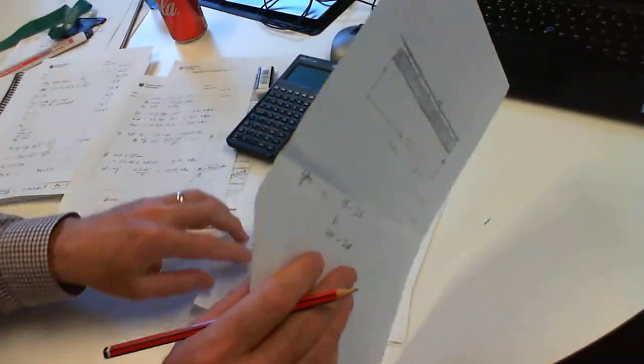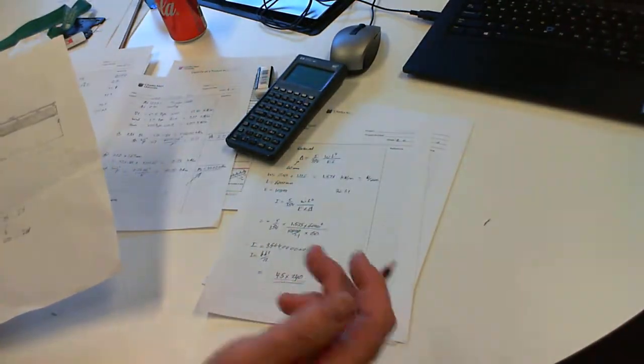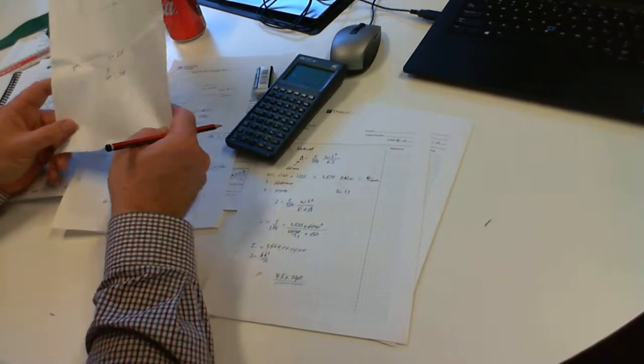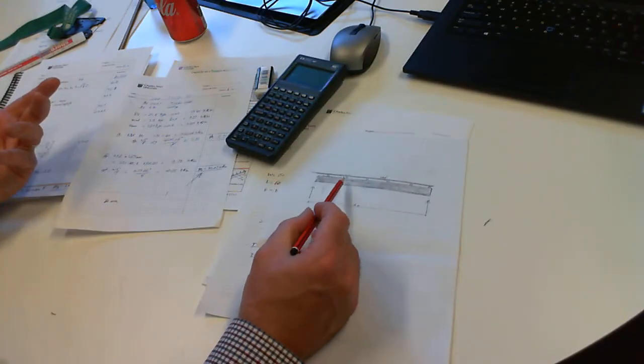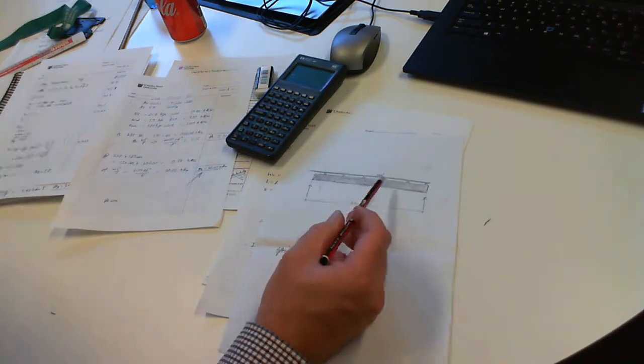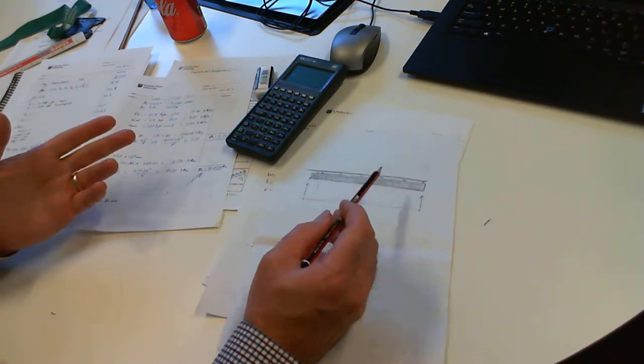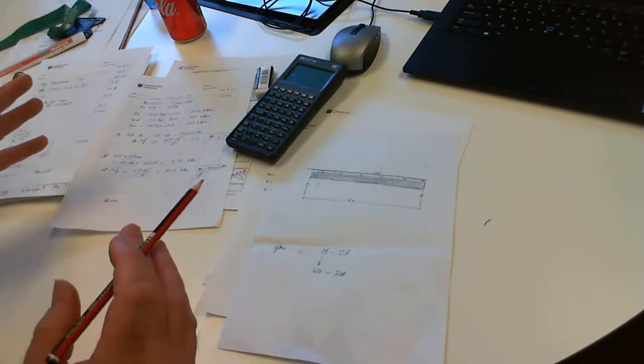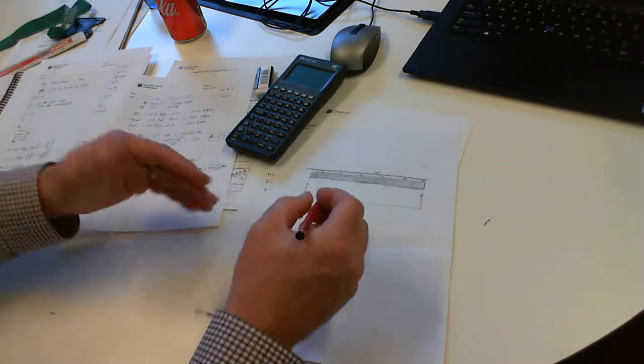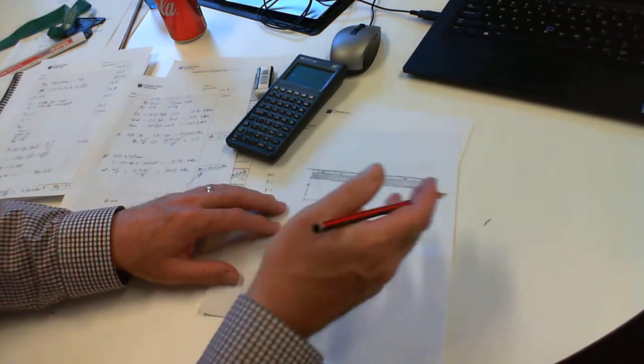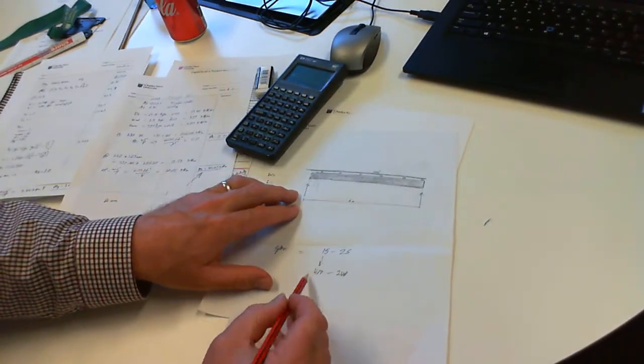Now, I am right at the upper limit of this. So this is towards the more slender end of where you should be. The reason I'm at the upper limit is we've got a fairly lightly loaded roof. We've got a whole lot of beams in parallel, so they're not heavily loaded. If this was a beam, say, under here, which was supporting a whole lot of these beams, you'd expect to be more towards the lower end.